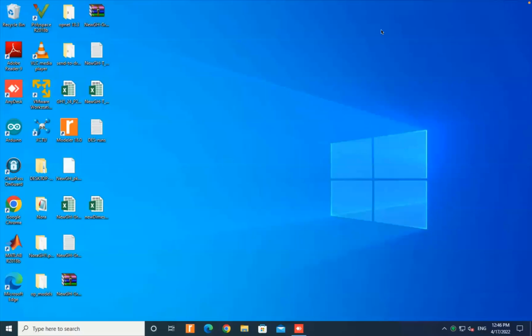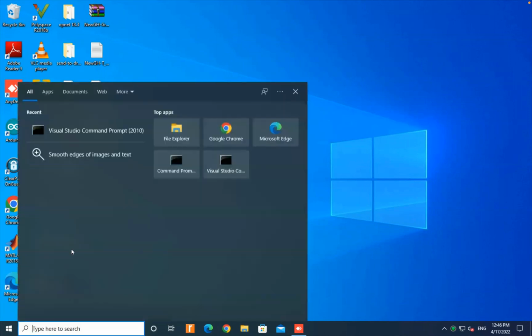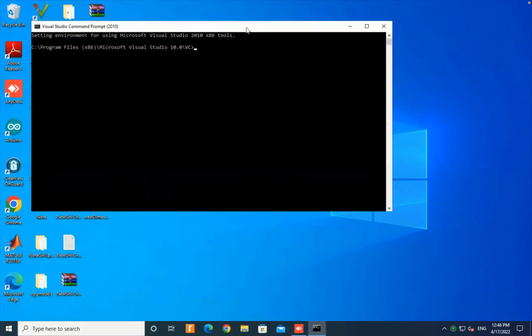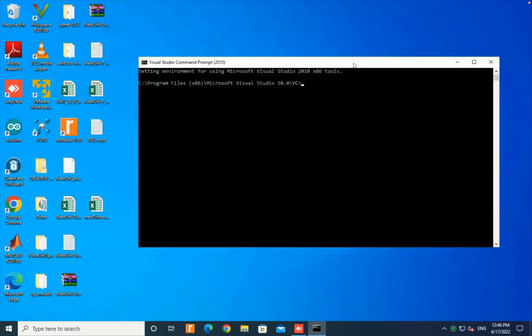Hello everyone. In this video, I'll give you a tutorial about how to make a simple network by using Opnet. Firstly, we will come here and search for Visual Studio command prompt. Run it like this. And then we will search for the modular shortcut. Modular is the new name of Opnet.